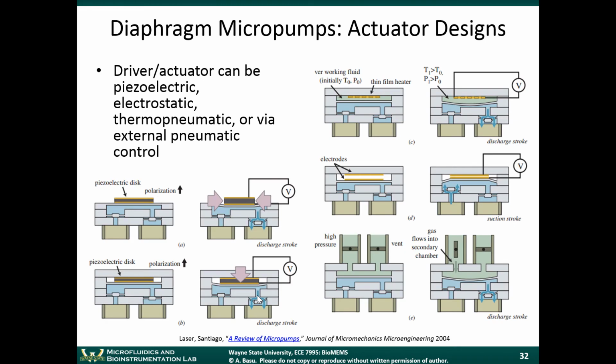So these diaphragm pumps, the basic concept is very similar to larger scale diaphragm pumps. And there was a lot of effort in the late 90s and early 2000s to create micro scale diaphragm pumps. And so that's the reason we're starting off with the diaphragm pump discussion today. So because this is, I would say, a relatively mature area by this point, there's a lot of review papers on micropumps. This is just one of the very highly cited reviews by Laser and Santiago. A review of micropumps was published in 2004.